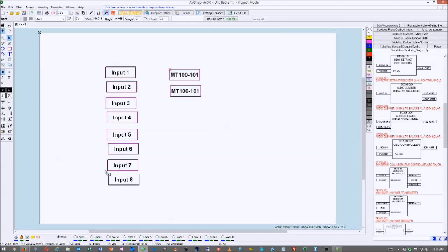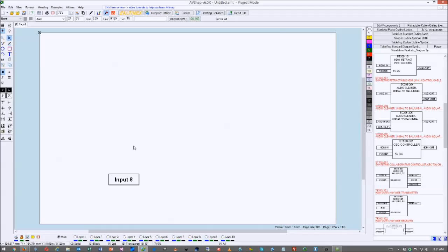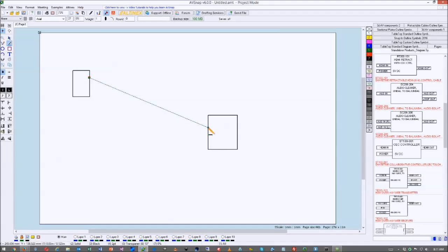I'm going to go ahead and delete this now, and let's go into the function called draw assist. Let's say I have two inputs right here, one input here and one output, and I need to connect the cable. One way to connect the cable is like this, and then you double click here and try to find the center and try to find the vertical. To avoid this, so that it's automatically adjusted for you, we have a draw assist feature.